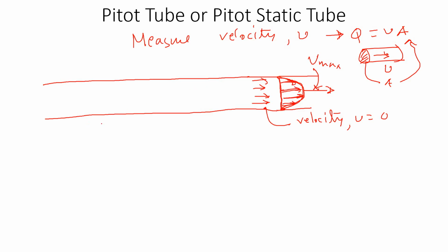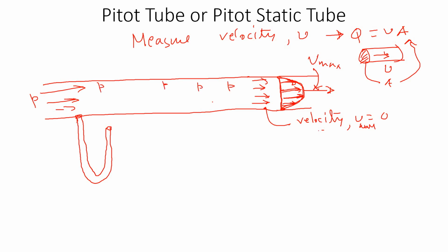So in the fluid, now think about this. We understand that velocity at the wall is zero and the max is in the middle. Now look at this. If I place a manometer here, a small one filled with water, and the air is flowing through that, this is a manometer, and I have a hole here. When the fluid is flowing this way, it has pressure everywhere. According to Pascal's law, the pressure inside this pipe, if we ignore the small losses, will be the same.